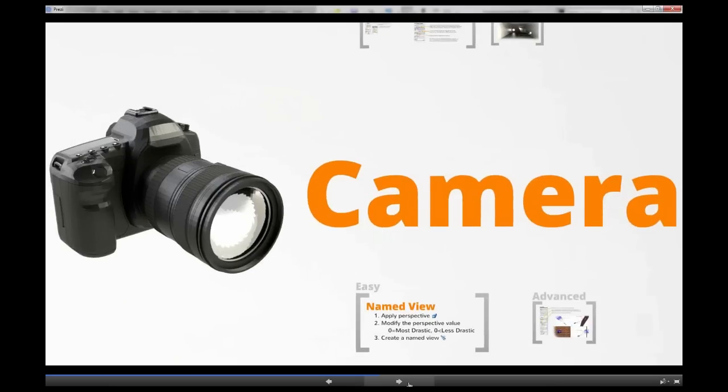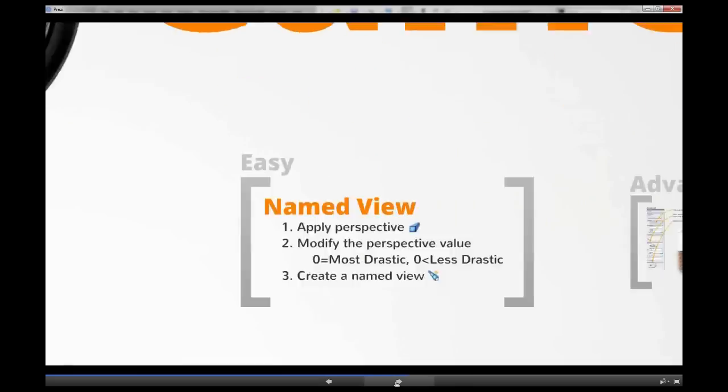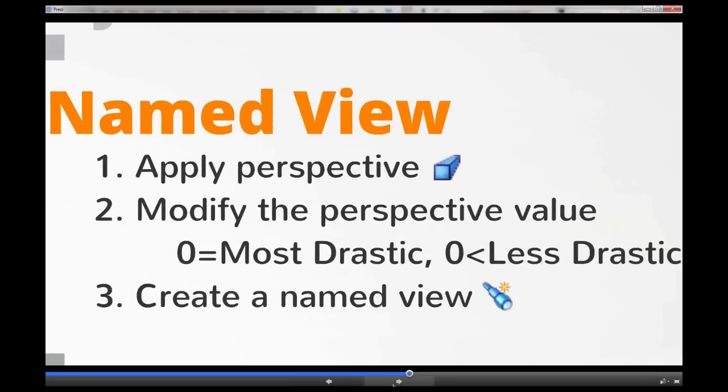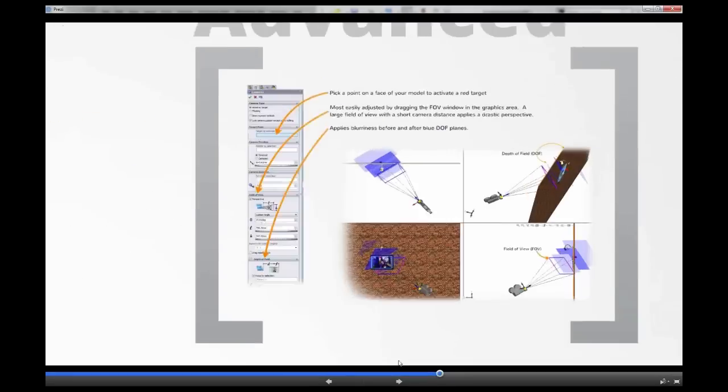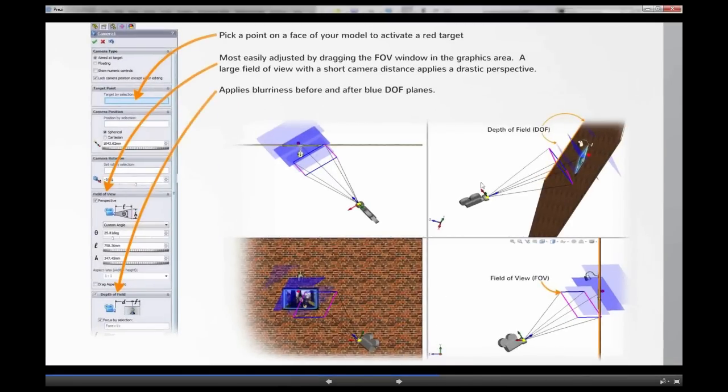All right, one of the last steps, and a very simple step, is the camera view. Now I'll skip ahead right here, there is a means of creating actual cameras, and there are benefits to creating a camera specifically in your model. But it does take a bit of work. You got to move the camera around in 3D space, you got to specify things, and the only reason a camera actually justifies its existence is with this functionality right here, the depth of field.